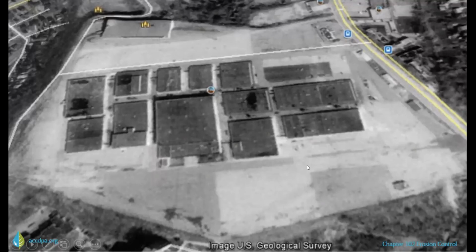This is a 25-acre site in the east central portion of the county and entirely impervious before development. When it was redeveloped, because over 1 acre of earth disturbance was proposed, a NPDES permit for stormwater discharges was required. The permit was submitted and reviewed by Allegheny County Conservation District, and during construction, ACCD performed 6 inspections at the site.